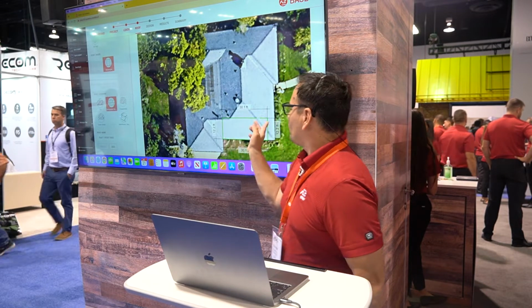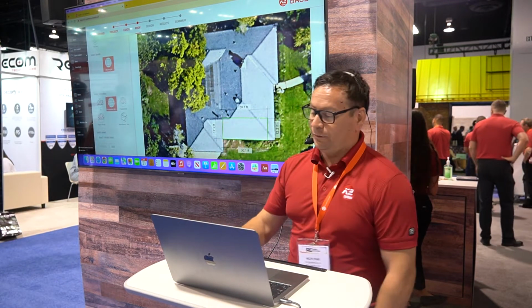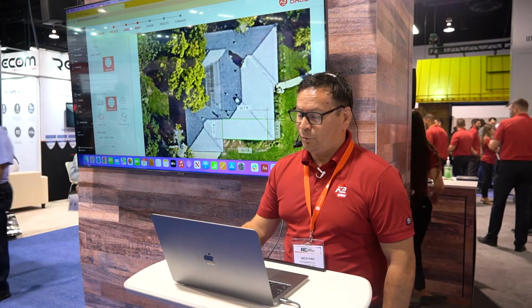After that, you'll notice here that my cursor has turned into a crosshair. I can zoom in a little bit further on the building, and I'm going to go ahead and right on the gutter edge right here. It has inline dimensions for you, so you can actually see what you're doing. We're going to shoot for just about 30 feet there. That works for me. And then we're going to go up the roof right here. We're actually not installing on that corner gable right here, but that's all right. We're trying to get as many modules as we can into this rectangle right here. So after that, I'm going to pull that up to the ridge. This is the surface area that we're going to be working with today.